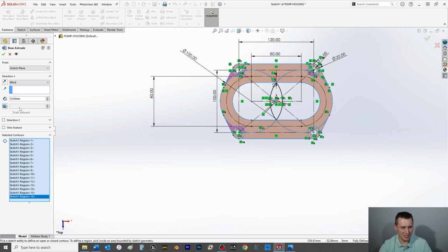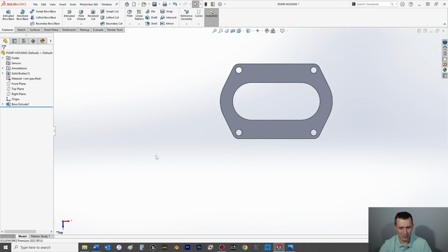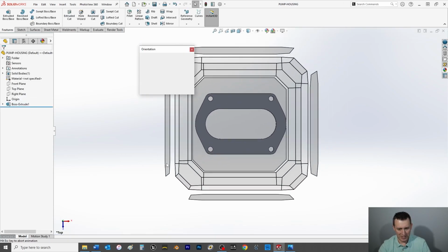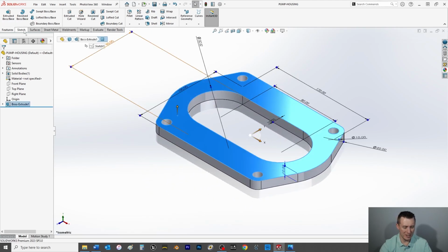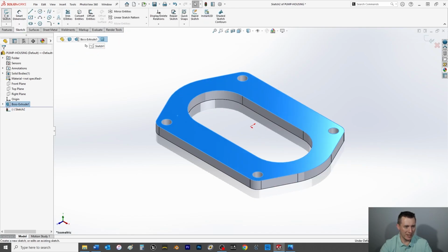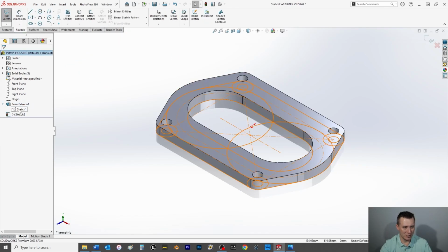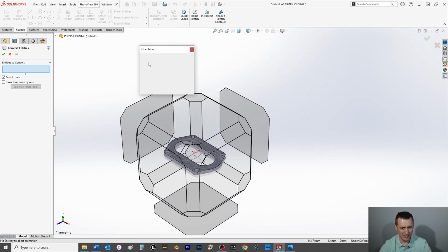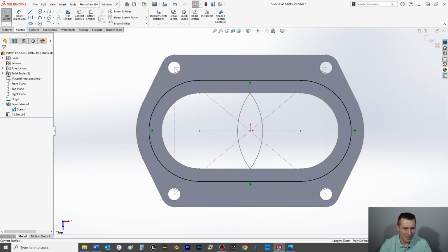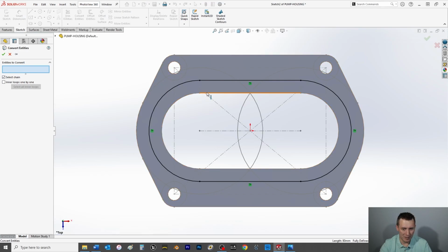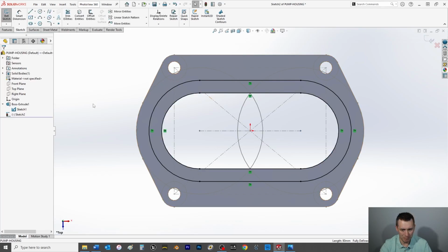Alright, excellent. So we're going to do a blind extrusion condition there. That gives us the first flange part, if you will. So now we're going to select this face here, and then we're going to go into sketch, and actually what I'm going to do here is show this busy sketch again. Convert entities. I'm going to bring it top view normal too so you can see what's going on here. Now I want to pick up this construction radius I made here, and then I'm also going to do another convert entities, and I'm going to pick up this internal edge here.